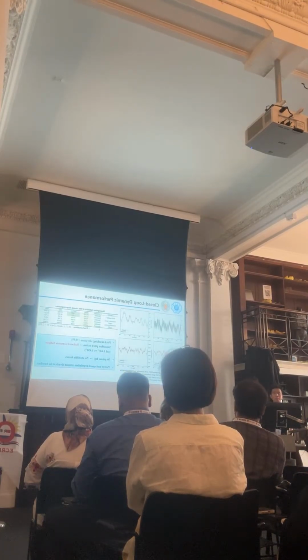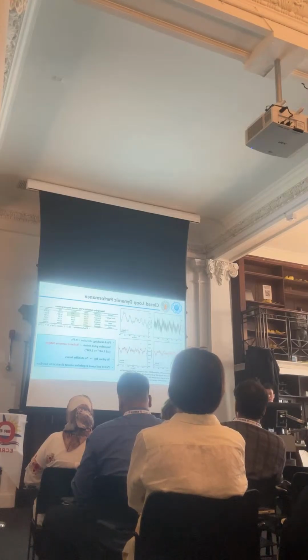And then we compared our RBF controller with the native OpenFAST CPC controller under the turbulent wind. As you can see from the time series plots, the pitch angle of our RBF controller follows the same trend as the baseline.